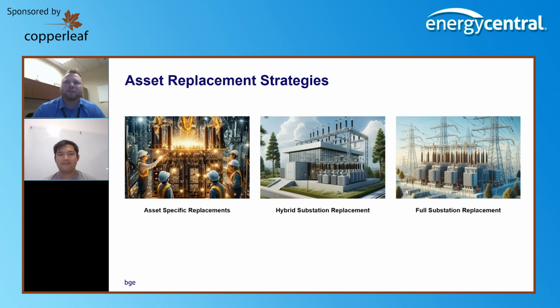It's allowing us to work outside of our typical outage season and drive efficiencies from that perspective. So we're evaluating now, what does that project look like in comparison cost-wise and value-wise to if I was just to go in over the course of a year and replace the 3 breakers that are brownfield in the bay. Those are some of the hybrid solutions that we're starting to evaluate.